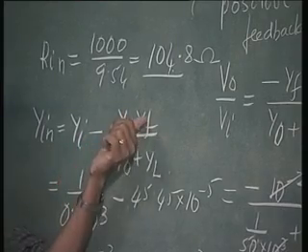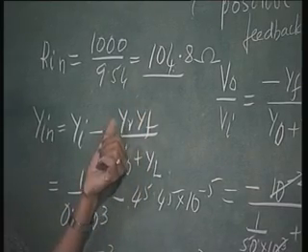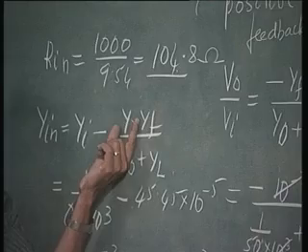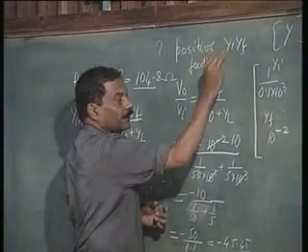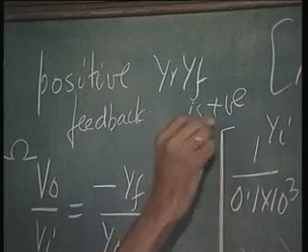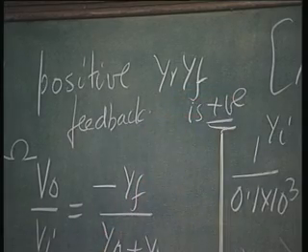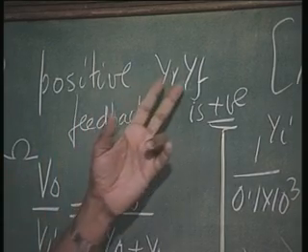Assuming these are positive, this becomes positive feedback only when YR into YF is positive. So we can quickly identify whether it is positive or negative feedback by seeing the product YR into YF.